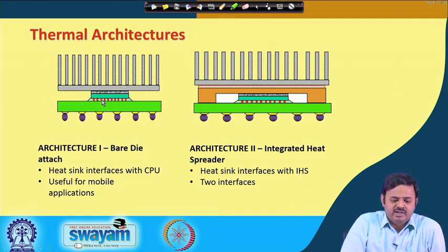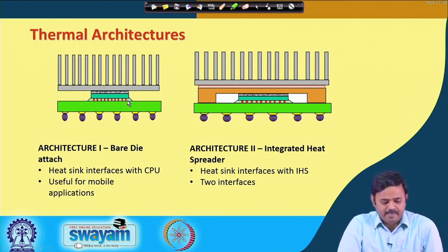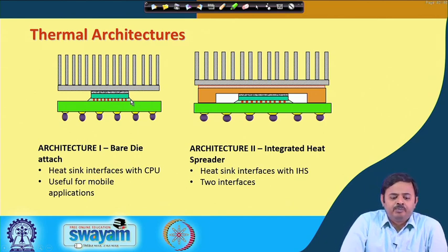So, these red elongated circles, as you can see, are the solder balls. It is a cross section, and what is around the solder ball is the underfill epoxy, if you recall. The silicon is flip chip bonded onto the substrate, and this is the underfill epoxy.